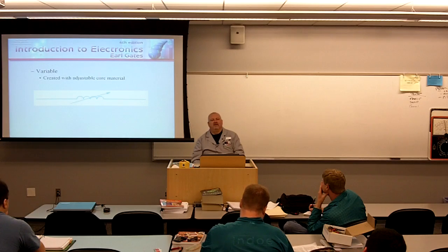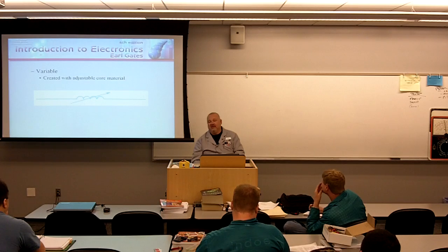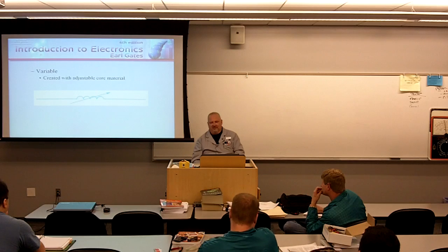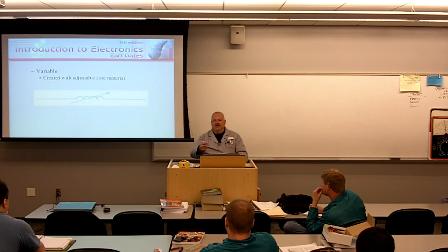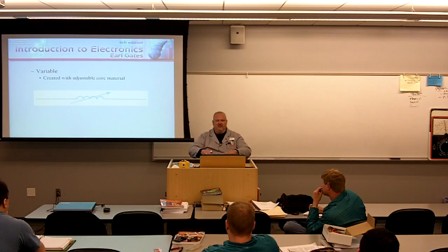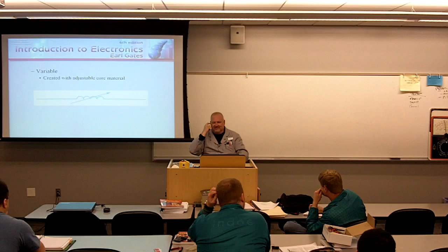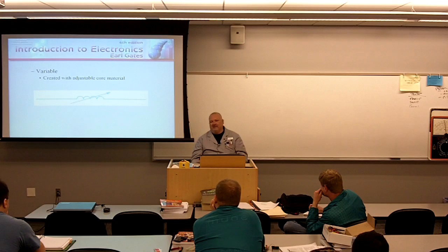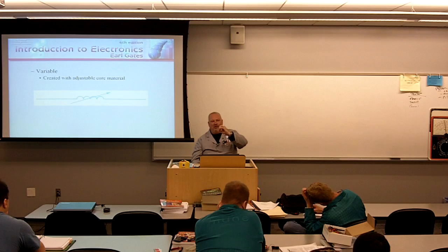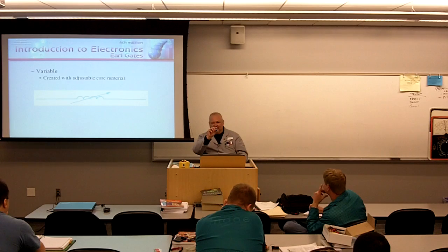Because typically the questions I used to be asked in a lot of my military Navy equipment schools, what we would have were circuit card extenders. So you would take the circuit card out, put it in the extender, and now the circuit card was mounted above the rest so that you could get in there and make adjustments. A lot of times you'd have to make the adjustments from the back side. They'd have a little hole physically in the board that you could put your adjustment alignment tool in.